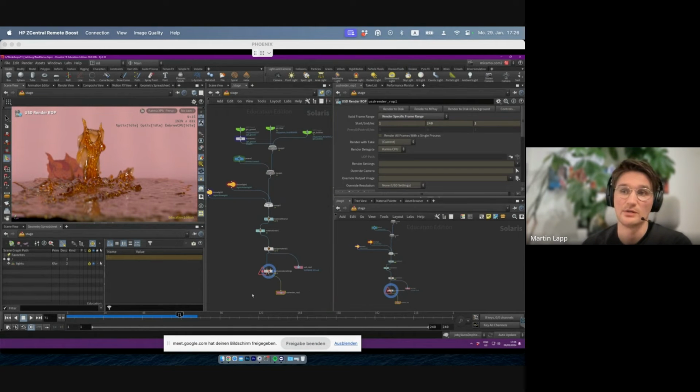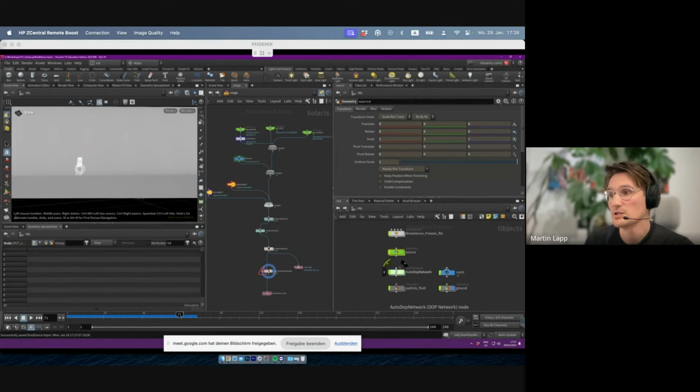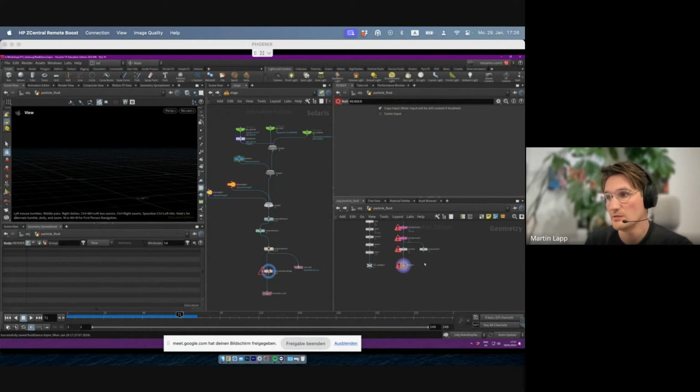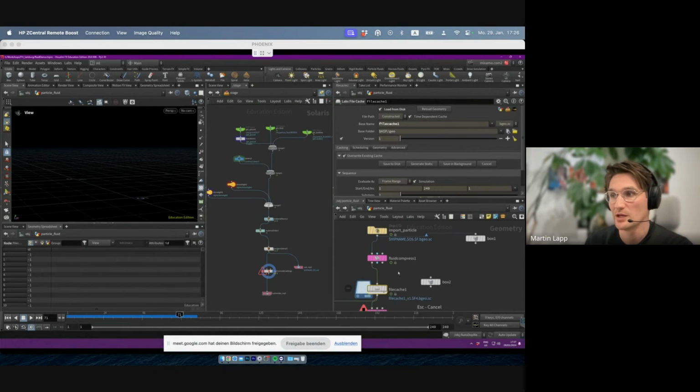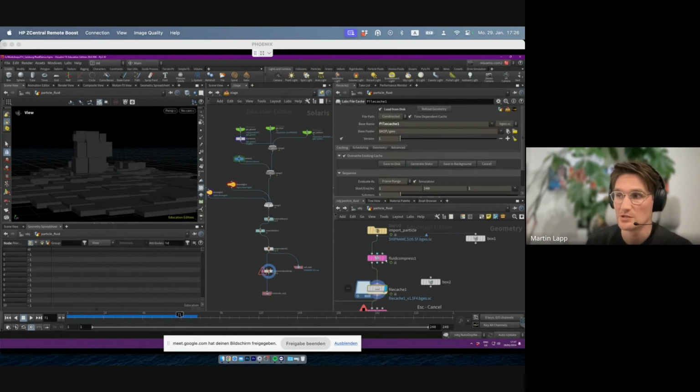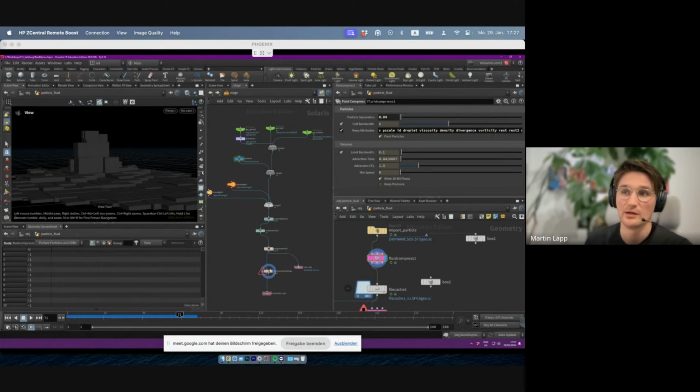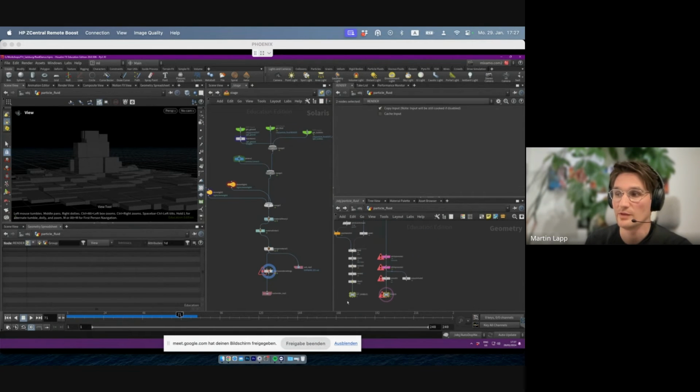And so it gets slower overall, because all of those 15 machines first have to sim and then render. On my local machine, it doesn't really matter because it's a single proc thing anyways. But on the farm, that's the reason why we would probably not render the final surface down here, because that's quite expensive. But we would export cache just this fluid compressed file cache here, which is basically looking like all the boxes here. And then all the stuff that happens after just takes like 1 or 2 seconds a frame.